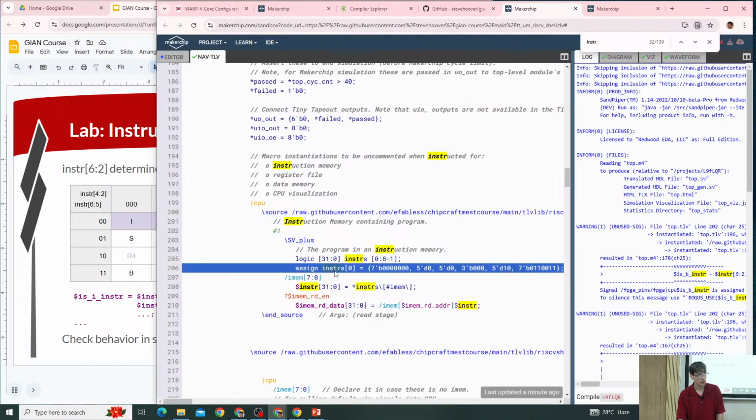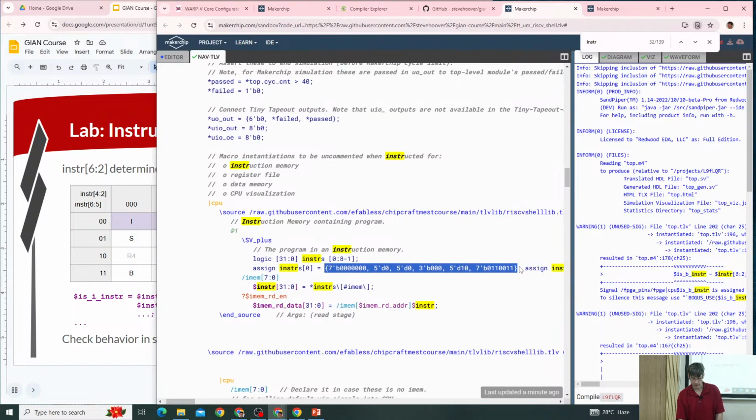You'll see there's an instruction array. This is using Verilog, and we're assigning the contents of that whole array. So this first expression is entry 0. The assembler has decoded the instruction and figured out all the bit patterns and generated this string for us to represent that. Yeah, this is going to be 32 bits.